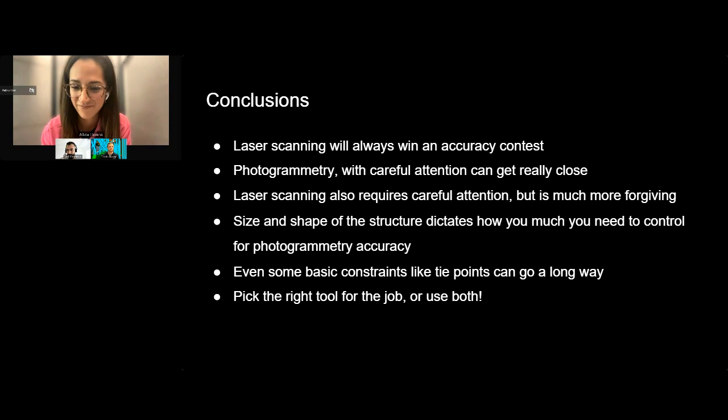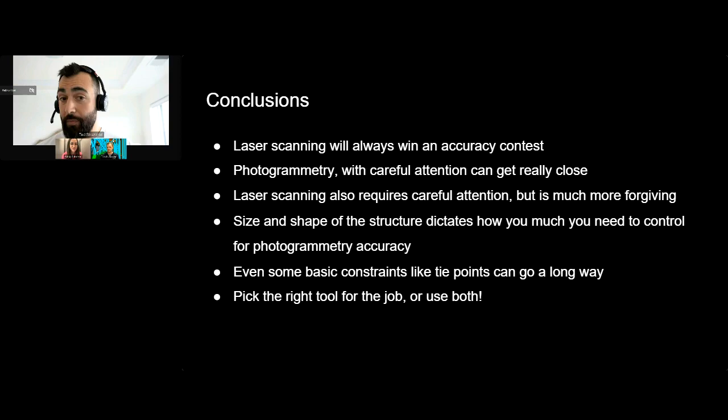Okay, so let's start here. I have a request from a client for archaeological purposes, with and without tree canopy coverage. What is my best option? I'm assuming that relates to aerial laser scanning. That would be a large area, you need to cover it, you have trees, you need something that can look through the trees. That would be laser, of course, right? For the areas where there isn't tree coverage, photogrammetry can work just as well. But the combination of both is going to be really tricky for photogrammetry.